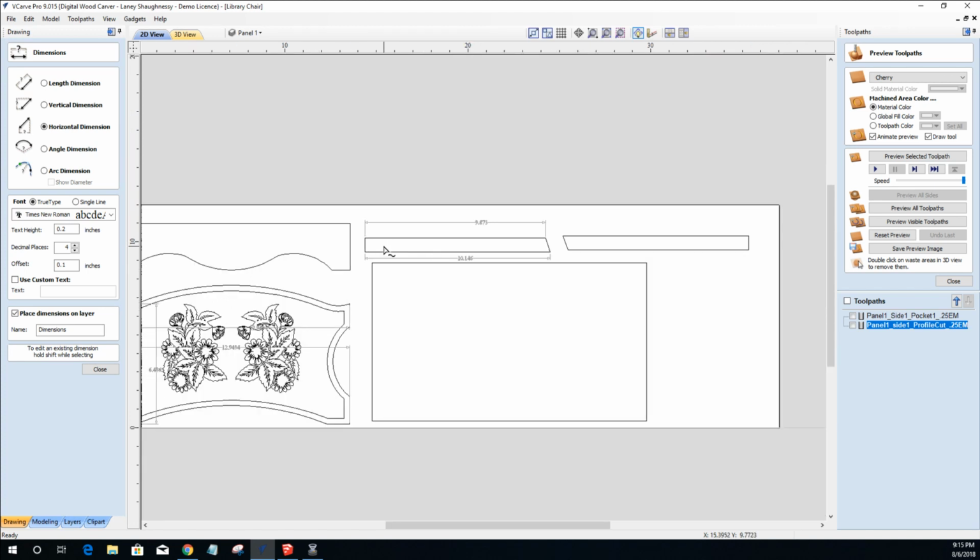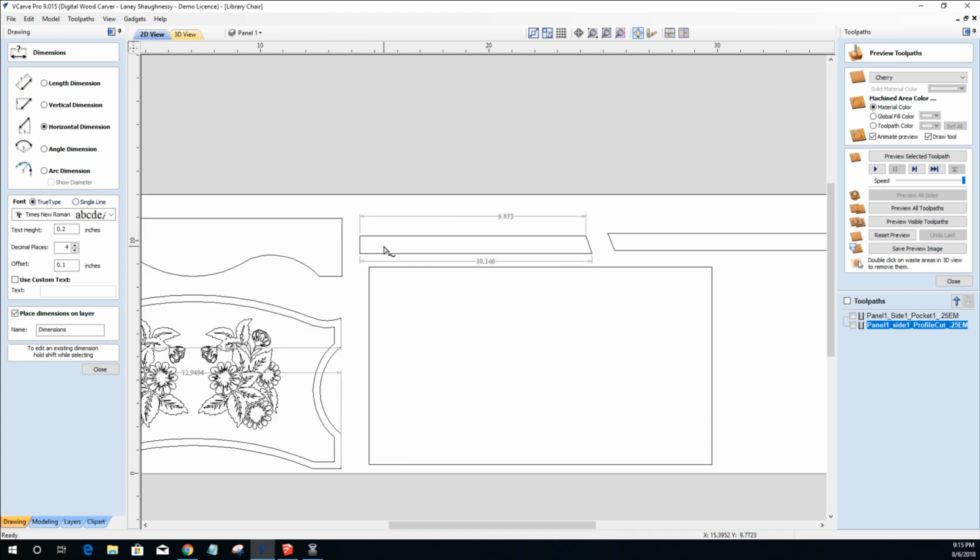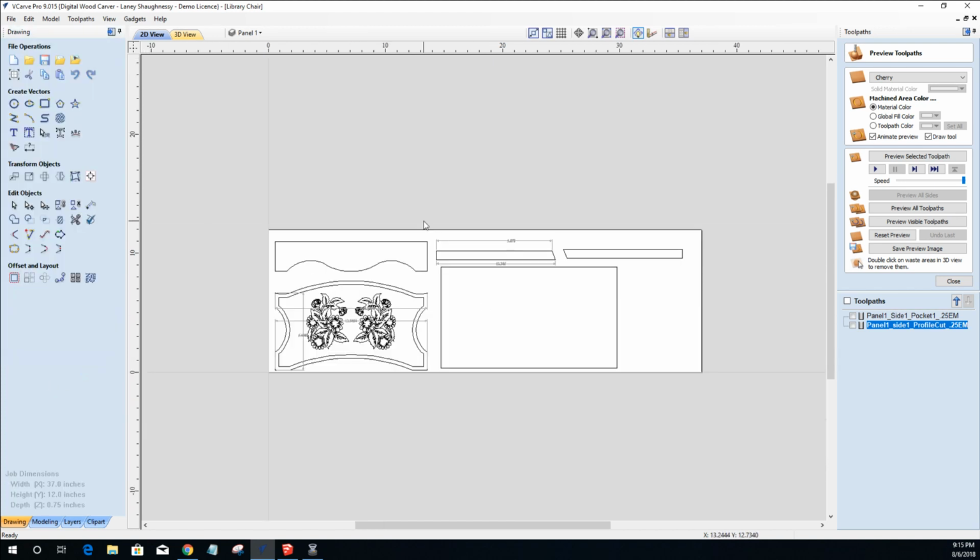It all depends on how deep your pockets are on those side pieces that it fits into. You can make this an even 11 by 9 3/4, because when it gets glued in, it's going to get trimmed with a flush trim saw on the back and on the front, and that's it. Those splines, you don't even have to cut the angle on it. You could just cut a square spline, put it in there, and then flush cut them when it's done. After it's glued up, I'll flush cut the scrap off, the overhang, with a saw, and then sand it nice and flush. So those parts don't need to be cut.